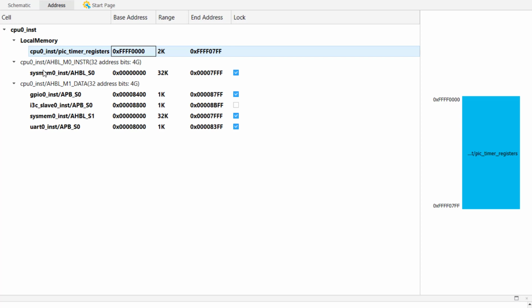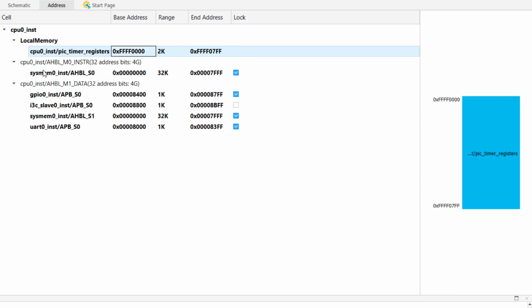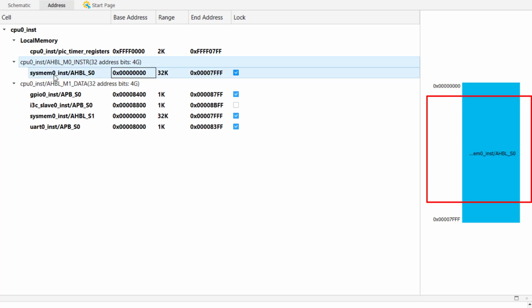memory map. The reason for this is because each component's memory space utilization is defined in that respective component's IP package configuration. Because of this, ports cannot show up in the memory map by themselves since they do not have any memory space utilization information that is associated with them. As mentioned before, Propel Builder's Address Space tab is divided into several different blocks for each interface connection. A useful feature of this Address Space tab is that if we select a block, the graphic on the right side of the screen will update to provide a visual representation of the memory space allocation for that memory block.